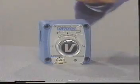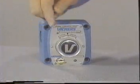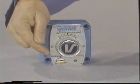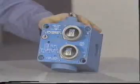Now, this is the unit that's both pressure and temperature compensated. The knob on the front allows us to set the throttle opening, and the key is a means of locking the setting. The valve is installed into the system by means of a subplate, which has matching in and out porting. Over here, we have a feed control panel, which in effect is 2 flow controls.